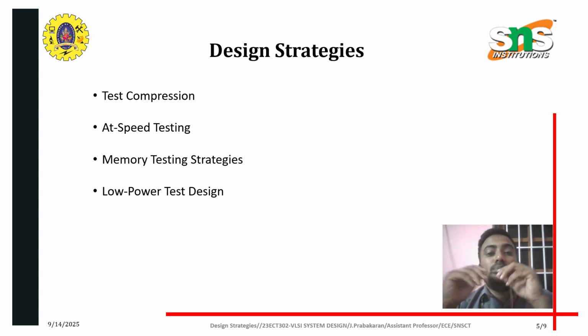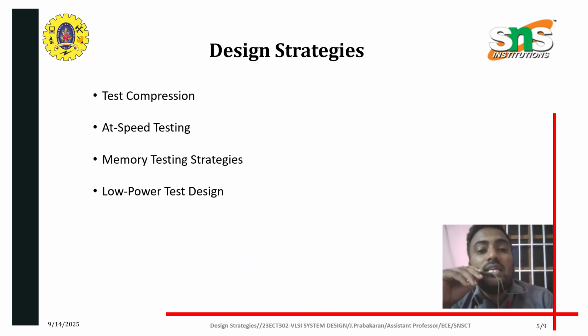Next design strategy is at-speed testing, which is required to detect timing-related faults like transition faults, path delay faults, all those things.